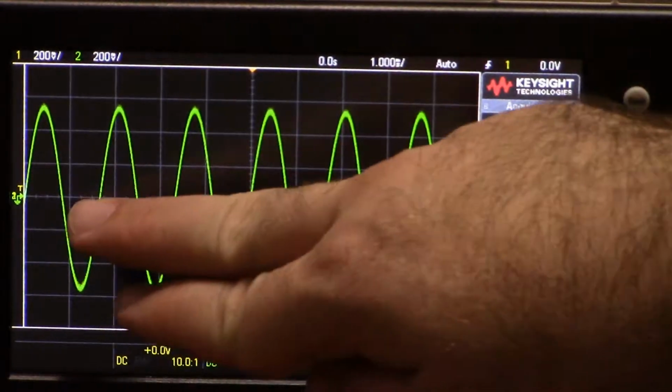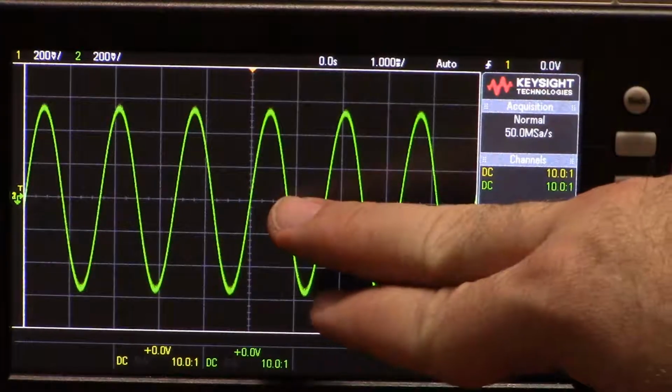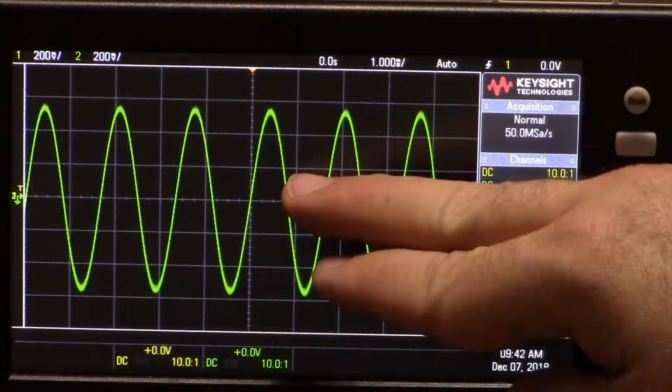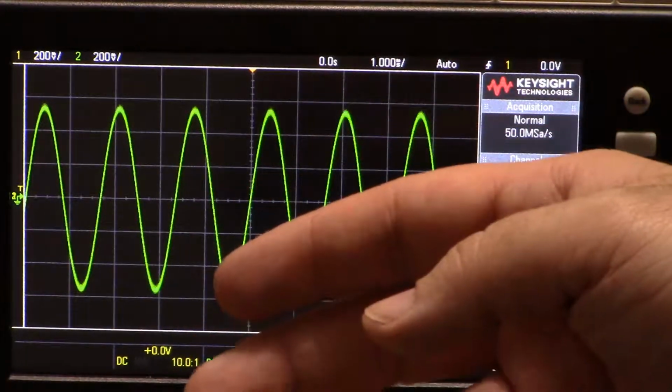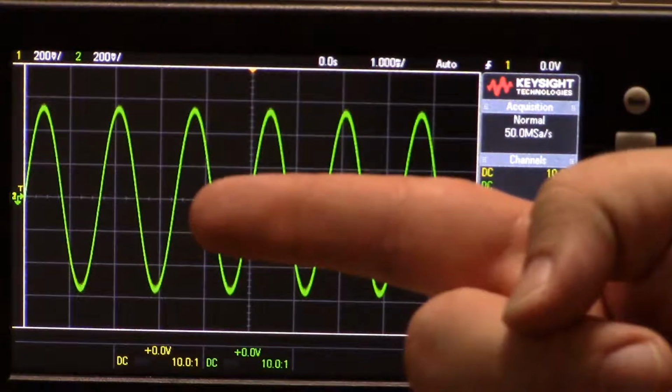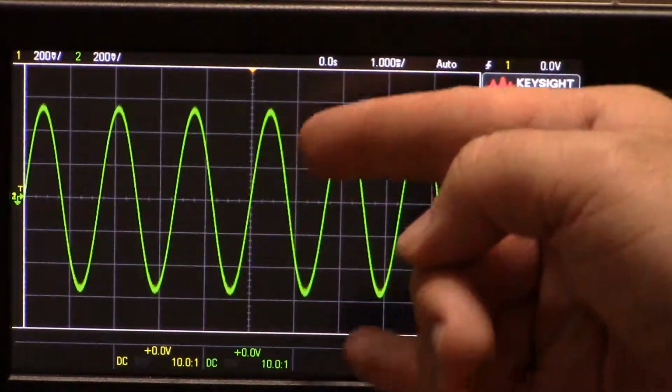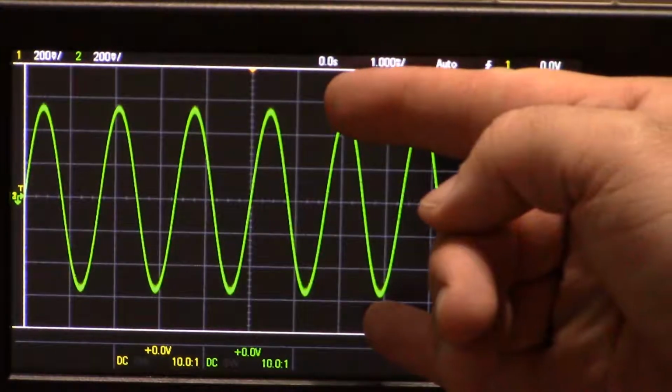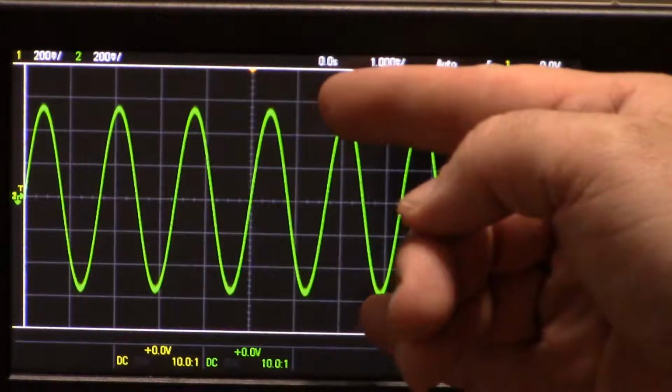So we established that we were getting about 500 to 600 millivolts peak to peak from the tablet. But I could not confirm that I was outputting maximum signal value. On here I can, so maybe the tablet would put out higher. It's entirely possible those sounds were just too quiet.